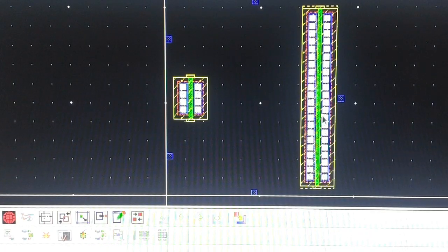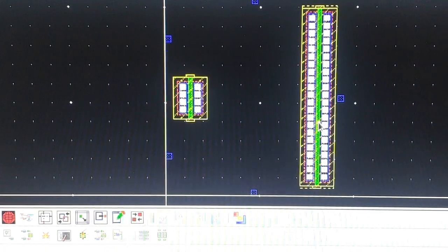So I understand this is the top MOSFET and the shorter width nMOS is this one, just looking at the size, and that will act as the bottom MOSFET. So now I know that this one will move on the top and this one will go down. Another thing that I know and I have to pay attention to, that the body terminals have to be connected to each other and then grounded together. So that is another point to be noted.